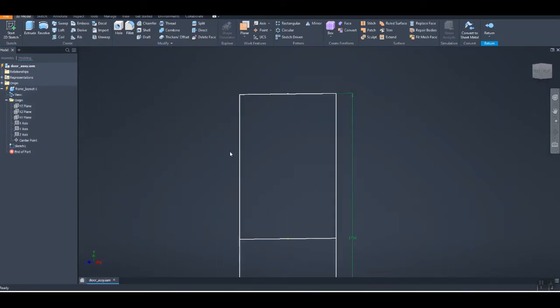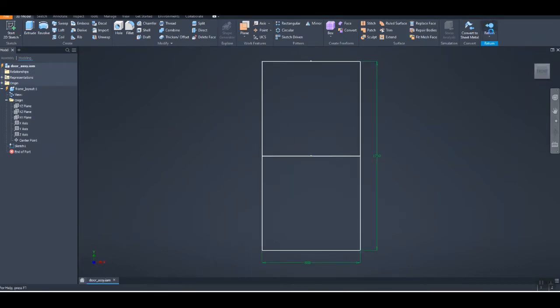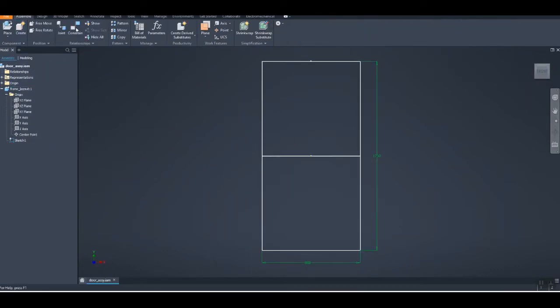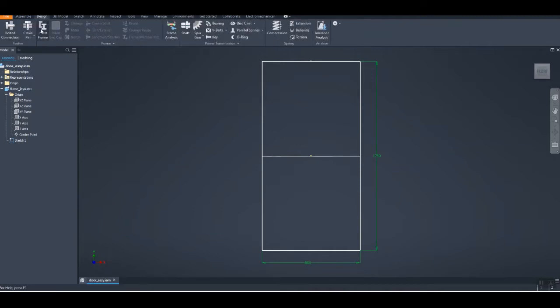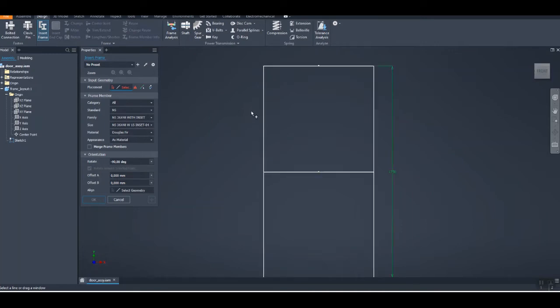Now I'm just going to use the Frame Generator. Go all the way back to the top. In the Design tab, you see Insert Frame. So inserting a frame, what I've done is I've made some custom family for the frame from the Frame Generator. Basically just made a profile of 36 by 48 with an inset of 15 mil. Let's see, Douglas fir.